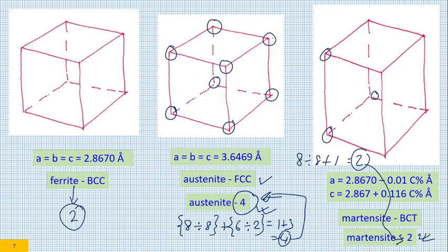During grinding, what happens? Temperature goes up. So if there is any austenite cell formed at the high temperature, when it is coming down to lower temperature, then martensite will form. Typically, most of the steel would be having ferritic structure at room temperature. It may have pearlite, cementite and all those. So those ferrites will transform into austenite at high temperature. Now once the temperature goes down, as the wheel goes out and the coolant is applied, this austenite will transform into martensite. This transformation, I am saying as a fact, would induce compressive residual stress.